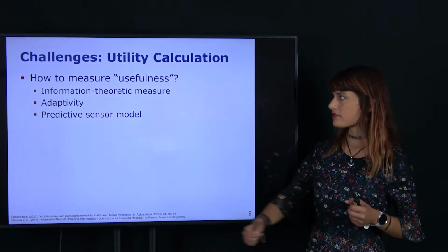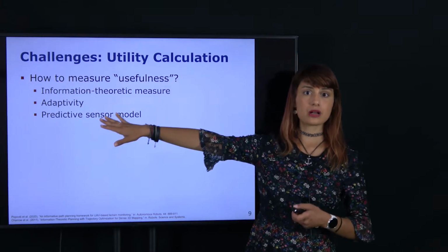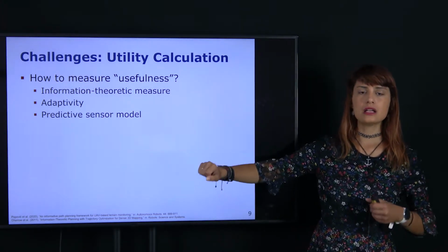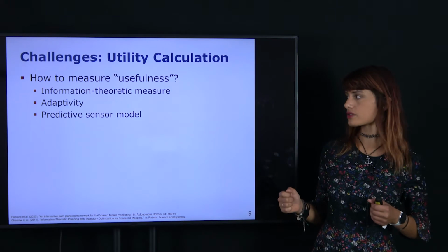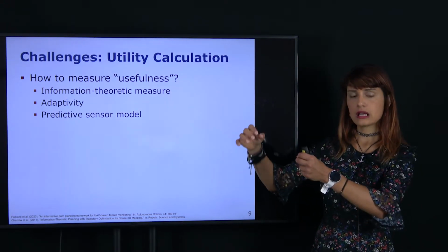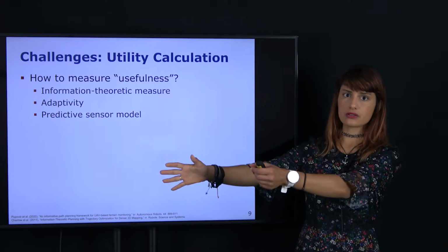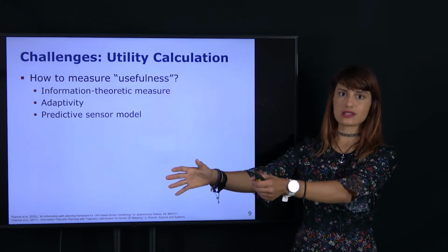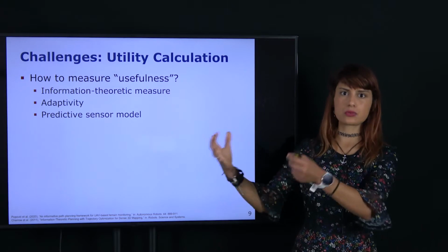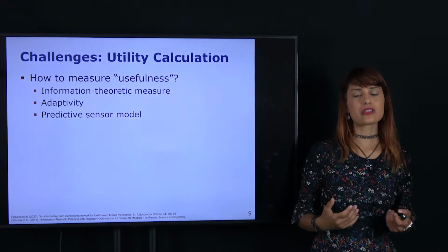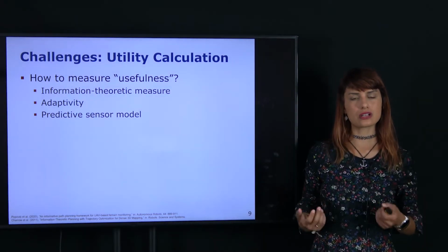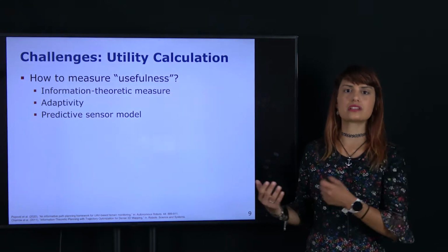An example of a sensor model, as we see later for exploration planning, is the camera field of view. So if we position the robot at a given location, we can project the receptive field of the camera in the current state of the map and use this to predict, for example, the amount of unexplored area that the robot would see were it able to move there.